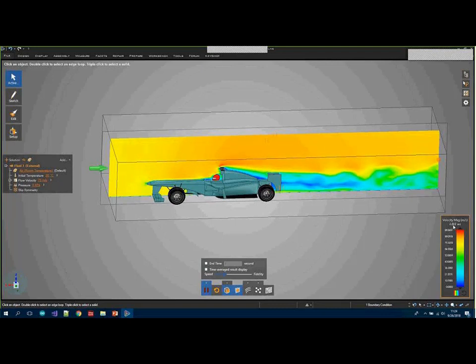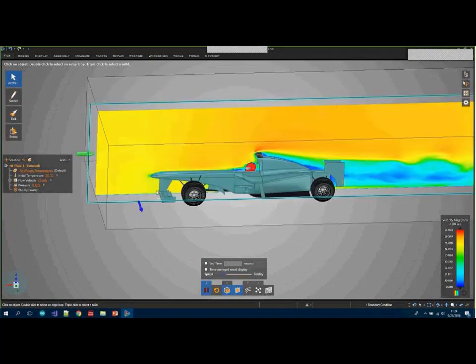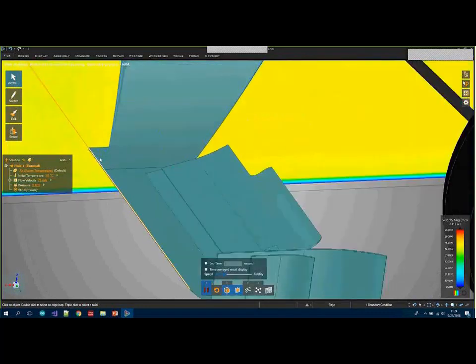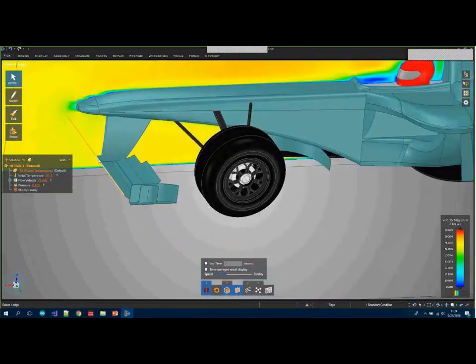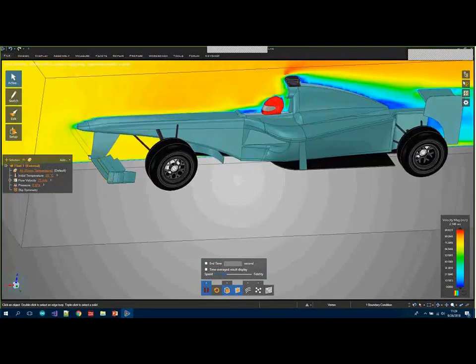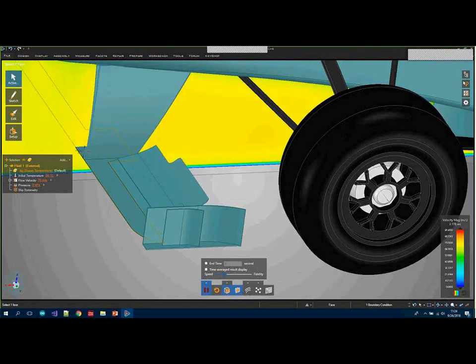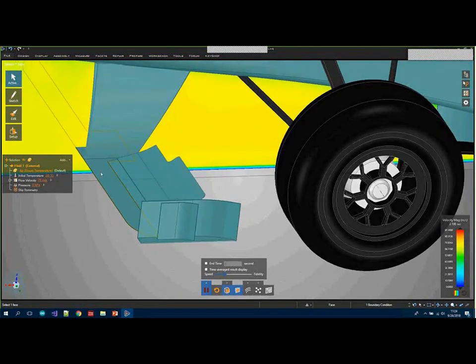Now, as you can see, we're about 2 seconds into the simulation time. We're on the speed side of this, not the fidelity side. So certain areas of this model may not be taken into account. What you'll notice here is this front wing is extremely thin compared to the overall size of the model. And so in those types of situations, you would increase the fidelity, or you may want to just test the front wing by itself.